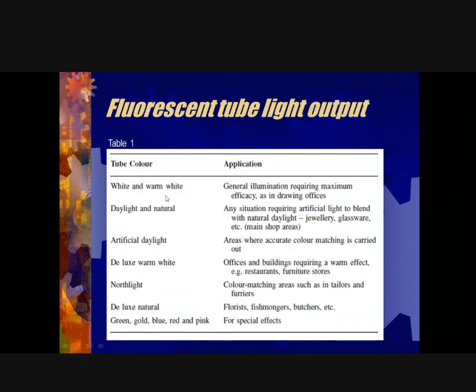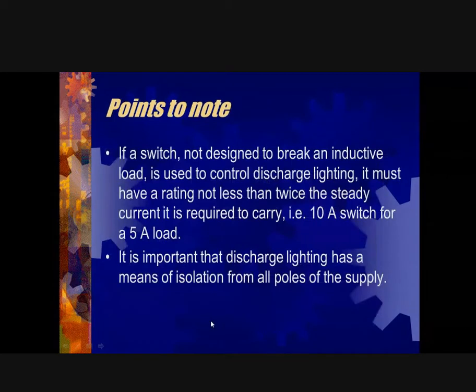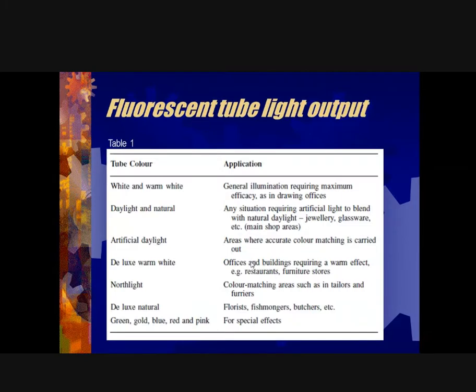Now, what the warm light will do is take care of the furniture and the person itself. It will show up the furniture and make the furniture look nice in the place. Whereas if it's a natural finish, it will enhance the effect of the natural finish. But I would have to consider the lumens in order to prevent shadows. That will come to your calculation; we'll come to that next. The position of the lamps, how you position them and the type, is going to determine how high it is in the ceiling.